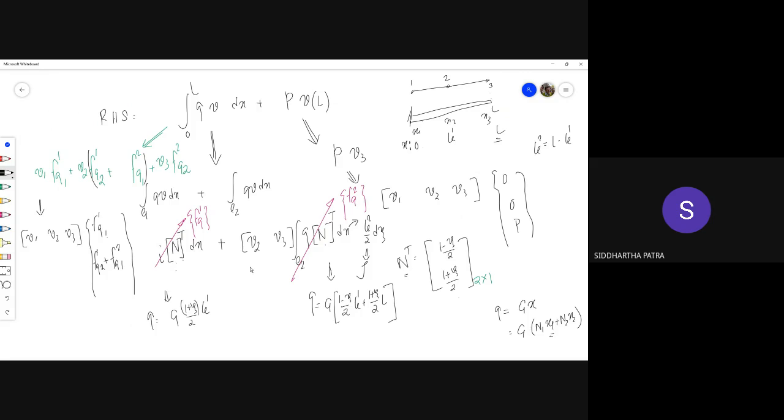Later on we would realize that we don't really treat x and y components differently. We simply number them, and this numbering, for example, if this is node number 1, 2, and 3 over here, is always counterclockwise. So this has 2 degrees of freedom, u1 and u2. This one has u3 and u4, and this one has u5 and u6.